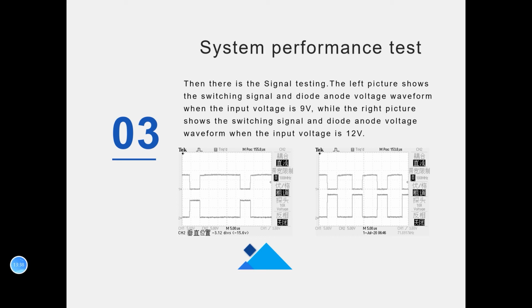This is consistent with the effect of the output voltage or input voltage on the duty cycle of the step-down switching converter circuit. The FET drain voltage waveform is complementary to the diode positive voltage waveform. The maximum voltage of the diode positive electrode varies with the input voltage, but the output switch signal of HV9910B does not change with the input voltage.